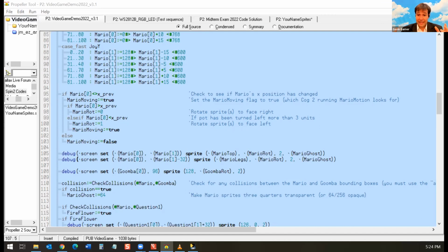And the other cool thing is he's added inline assembly to this Spin 2 language. So if you want to be running your Spin code, which is again just kind of like the C you'd see in Arduinos and stuff, it's a very high level, easy to use language. And then when you want to pull out the stops and just have it run at a blazing 6 nanoseconds per instruction, you just jump into a couple assembly codes and then jump back into your Spin. So it's really easy to go back and forth.